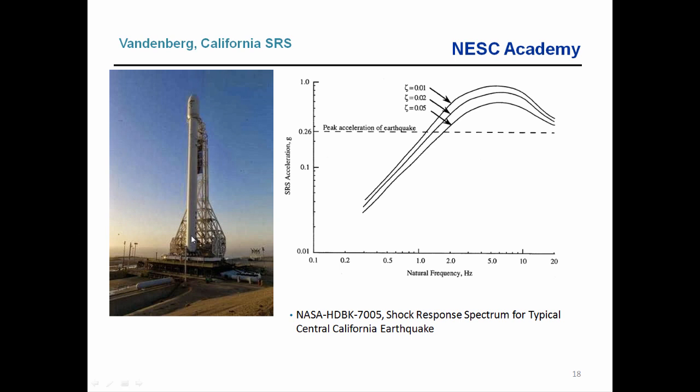But you have to remember that depending on the launch vehicle and its payload, that could be $1 billion. This launch vehicle is like a tall cantilever beam mounted to the ground. So if the ground starts shaking, that's going to excite the bending modes of the vehicle and could overstress the joints or the payload or cause something else bad to happen.